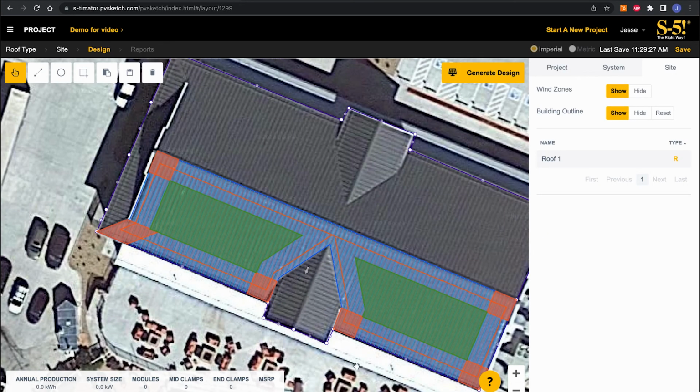And that doesn't mean you have to put solar across the entire roof. We can, of course, define down with the combination of setbacks, deleting modules, obstructions, areas that we don't want solar. So we can still have the array size and the array shape and the area that you want it. You just wouldn't do it by not drawing your roof over the entire roof. This just helps calculate the most accurate conditions that the whole building is going to be under, and of course that includes the roof.